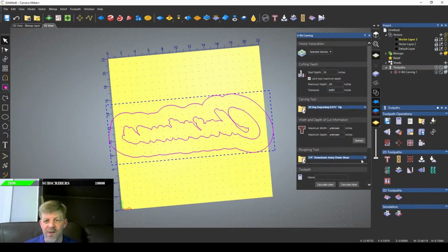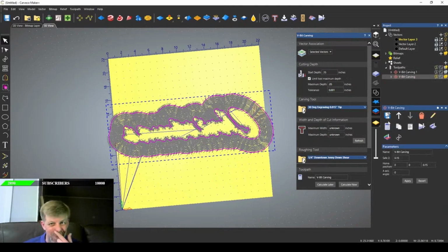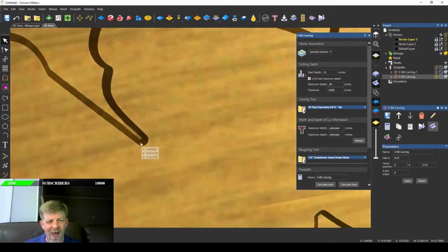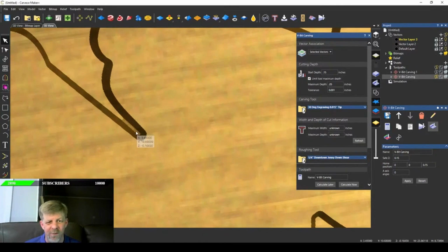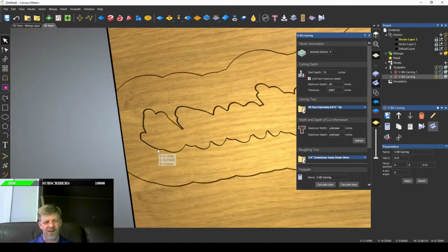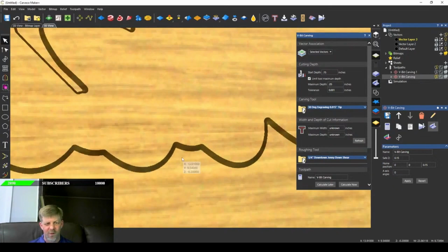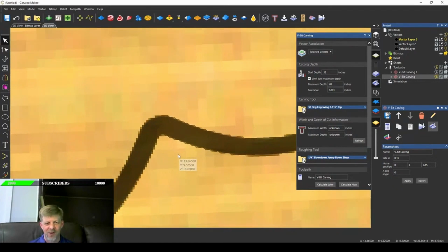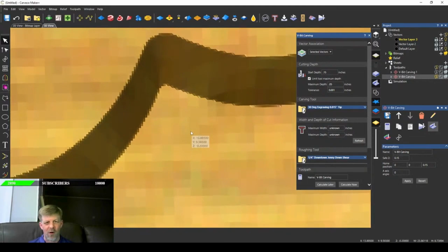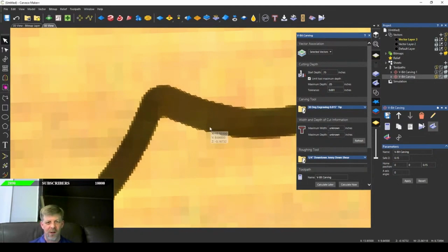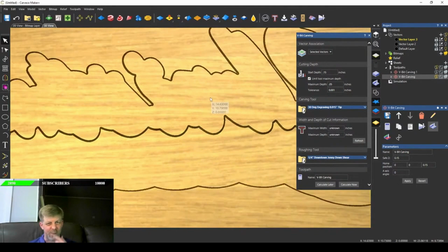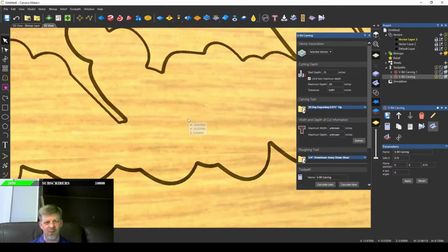Okay, we've got everything set. And that carved around that lettering to give us our male piece. Now, on the male side, if you get a little bit of stuff at the bottom, that's not really important because it's so far down that it's not actually going to be inside of your inlay. But because we started at the 0.15, we've created that chamfer or that angle on our walls that is going to allow this piece to fit into the other piece.